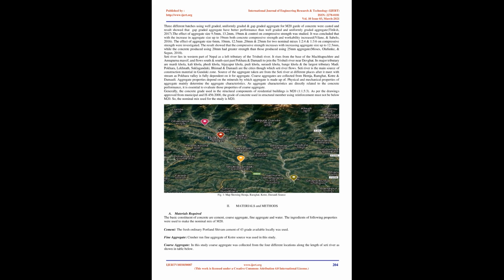3 different grades of nominal mixes: M1, 1:2:4, M2, 1:2:3, and M3, 1:1.5:3, by weight. Water-cement ratio, cement, sand, and water were kept constant while coarse aggregate source was variable. Due to variation of source only, variation in 28 days target compressive strength was found up to 47%, Prajapati and Karanjit, 2019.